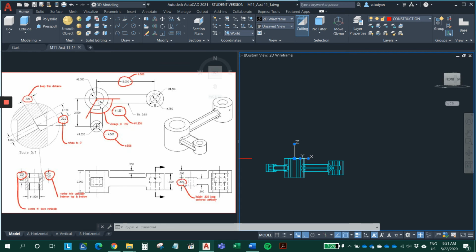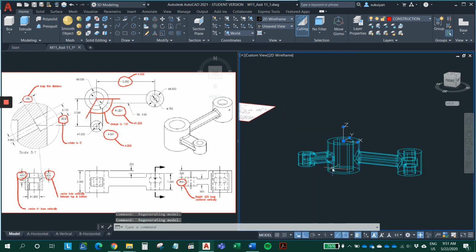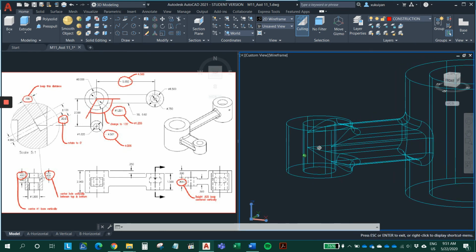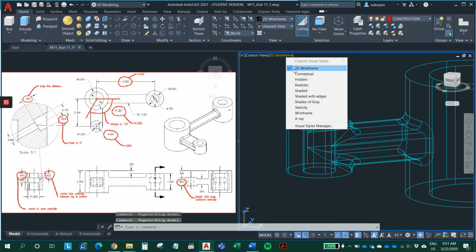The last one is going to be the height of this small cylinder. All right, we're going to change the height of the cylinder to 0.825 inch and make it always centered. In that case, we're going to use 0.825 minus 0.8, and we have 0.025 divided by 2. This is the distance we need to move the top and bottom surface. All right, top and bottom face.